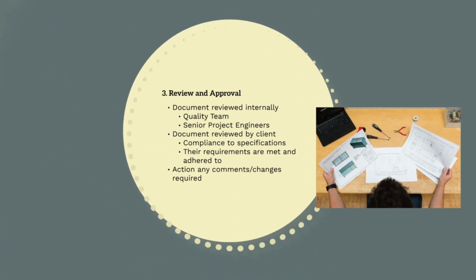Now our ITP has been completed, we'll need to submit it for review. The first stage of review will occur internally, when we submit our ITP to senior project engineers and the internal quality team. They'll complete their own checks to ensure it covers all necessary checks. Once they are happy, it will get submitted to our client.